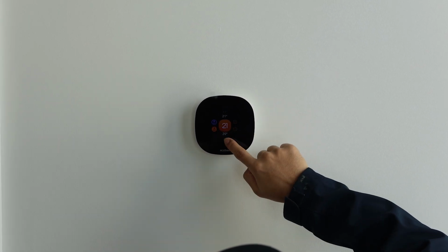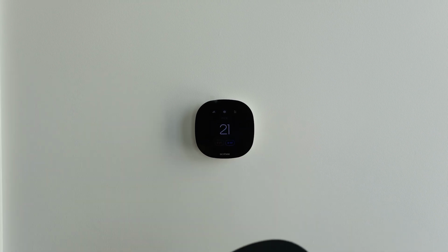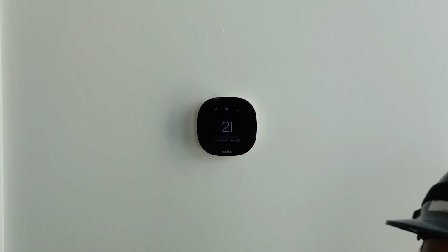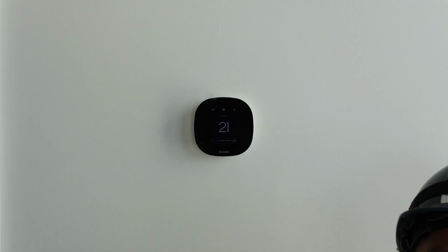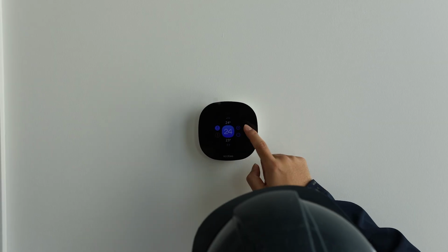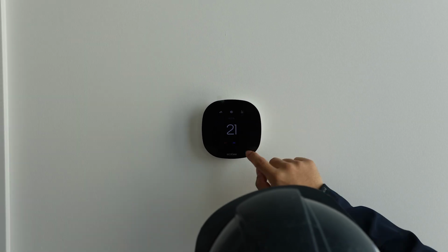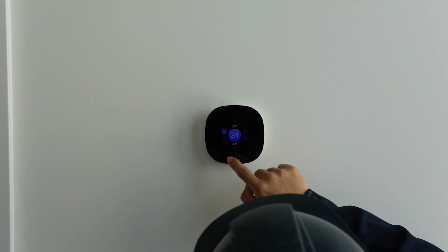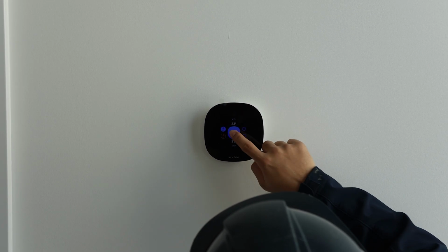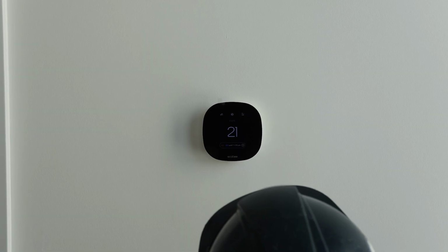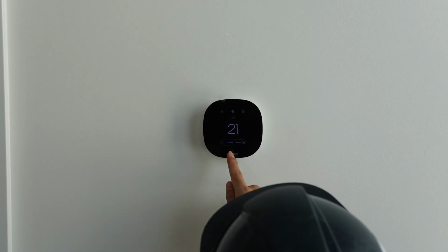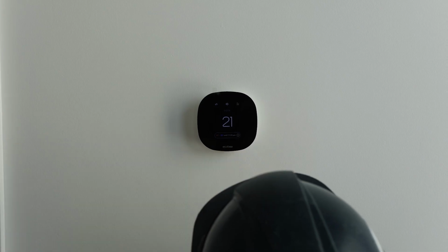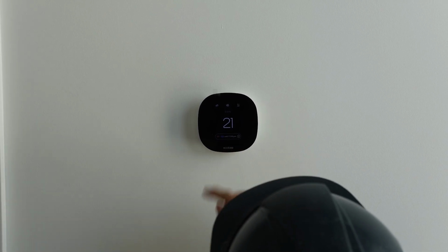And heating set point, I want to be 21. It can switch heating and cooling mode automatically. Here it also has, for example, right now I'm in auto mode. I'm changing the cooling set point, let's say, to 23. I hit yes. Now it's a temporary change. The setting will revert back at 11:30.